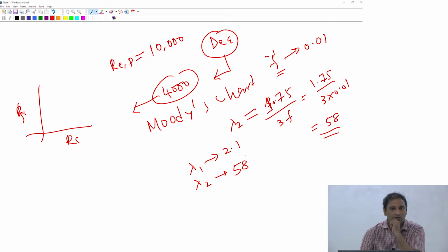The fact that this lambda 2 is much larger doesn't mean that the pipes are more tortuous; the pipes are as tortuous as in the laminar flow conditions. However, because of the turbulent flow condition, there are going to be a lot of changes in the area.